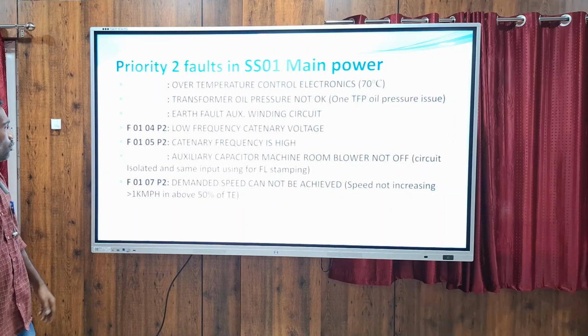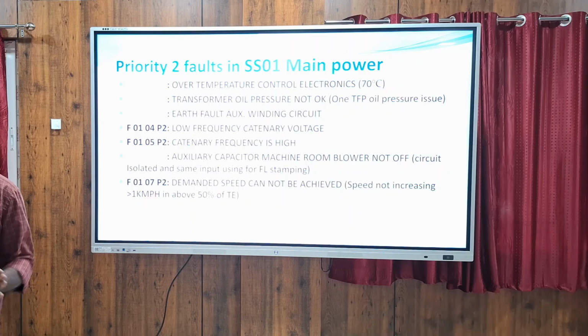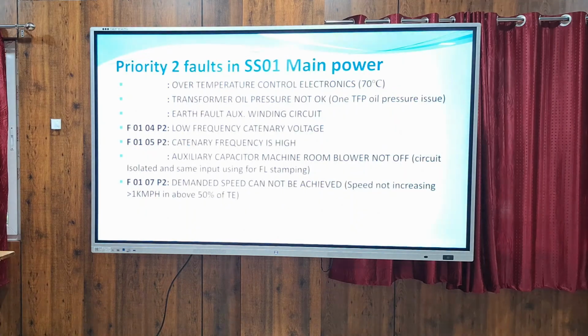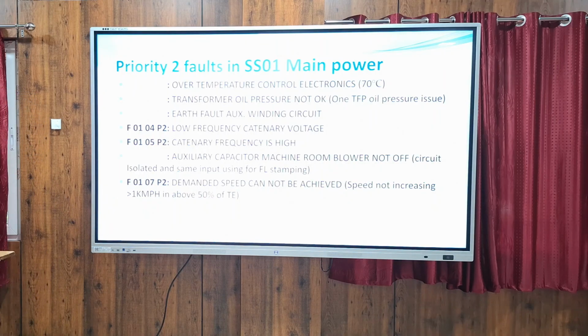Low frequency catenary voltage and catenary frequency is high. Actually it is designed for 50 hertz, and some tolerance is also there. Exactly I don't know, something like plus 4 and minus 2. So if the frequency is beyond this limit, this fault will come.